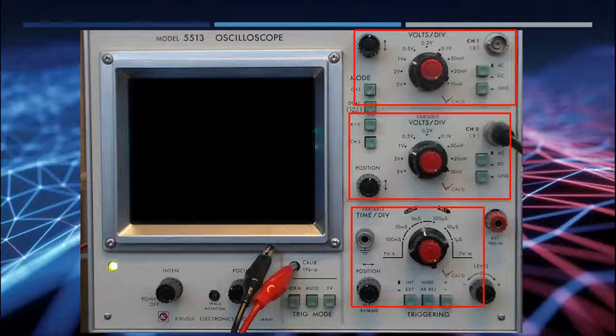The fourth area that you should remember from last week is this area where we will be able to obtain our predetermined signal. In the case of this oscilloscope, our predetermined signal is gathered from this area right here, where it shows calib. And what we see here is that this signal should have a 1 volt peak-to-peak output voltage. Good job.